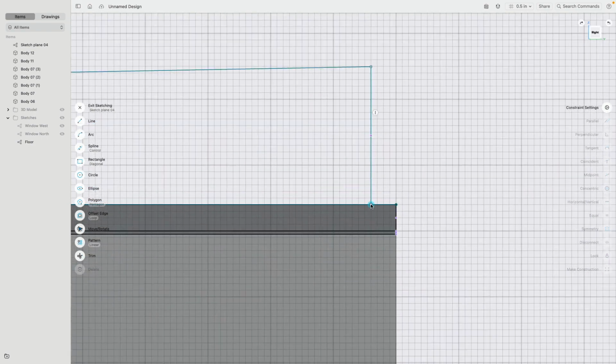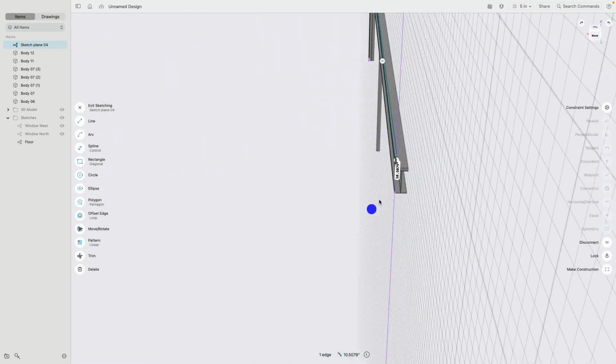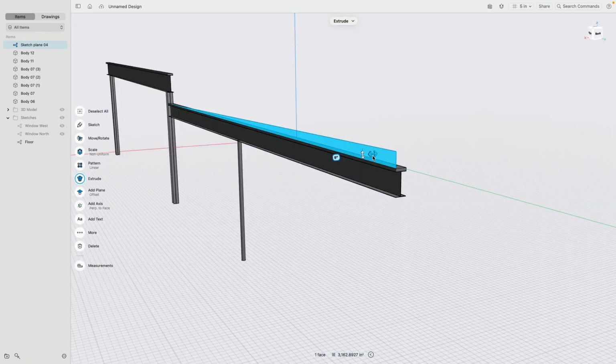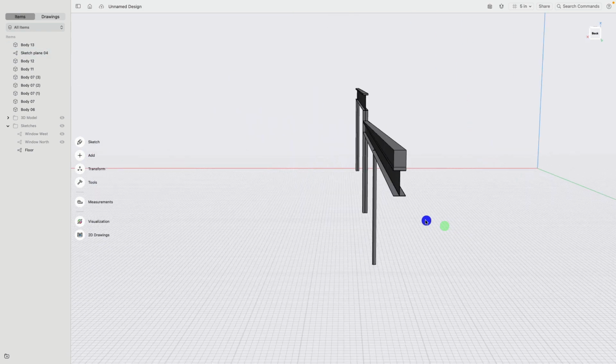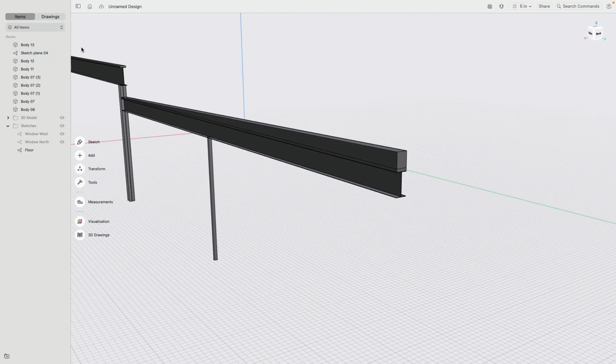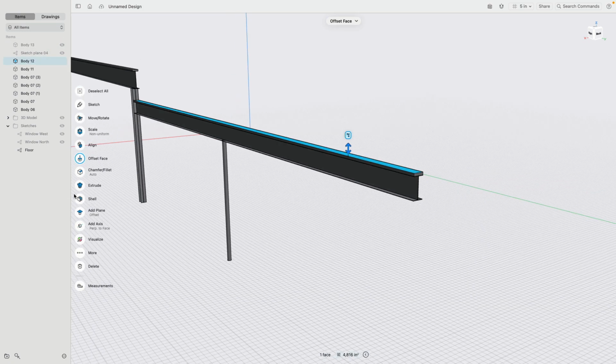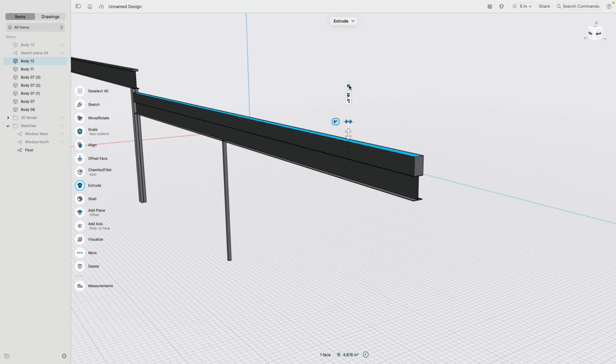And then what I will do is this point, I will snap to the end point. There we are. How do we have? Yeah, 10.5 inches. Okay. Very good. Okay, so then this we can simply extrude by 8 inches. So there we have this piece that sits on it. Now let's actually turn this off maybe for one moment. We do this exercise the other way. So you don't have to do this. It's just for you if you want to see it. So 10.5 is what I imagined. There we are.